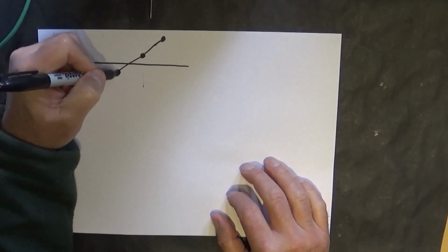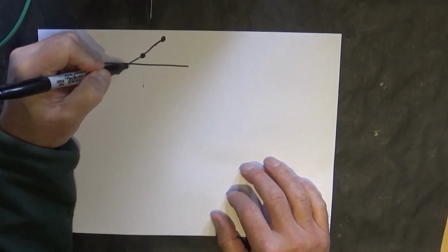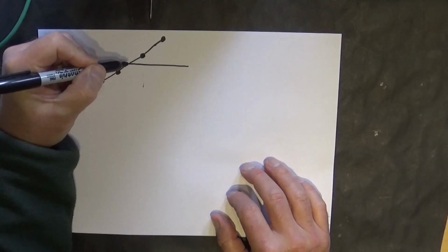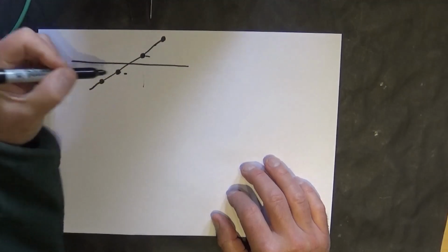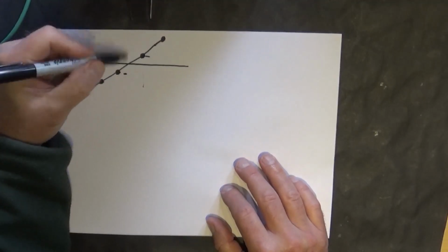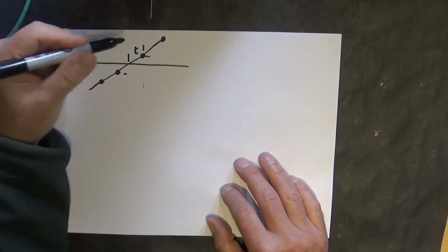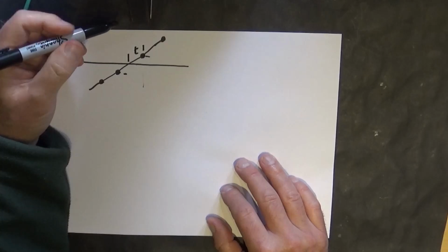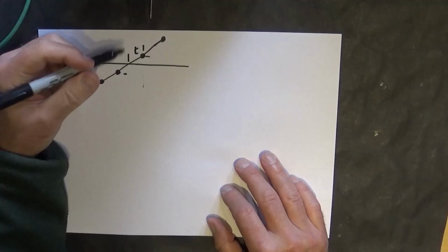So we can assume, because we don't have any choice, that the waveform was a straight line between them. So if we know this value and this value and this value, we can calculate that time as a fractional sample. So in the picture that's a half.